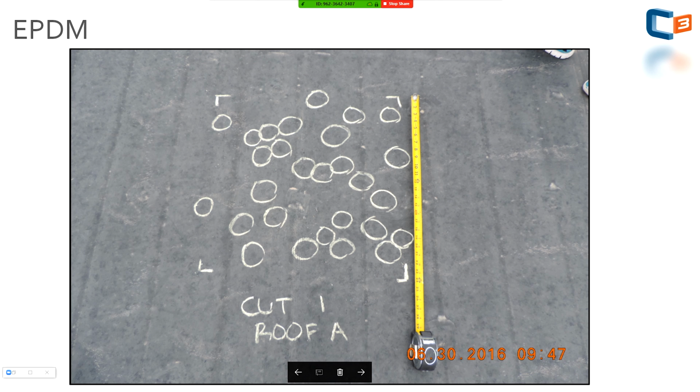So what I'm doing in this case, I can see that spatter mark. I had good collateral damage, and I'm going down and I'm trying to feel the substrate condition. If it's depressing downward, I'm going to circle those areas. Those spatter marks are evident. I can see hail impacted area. And if I find a corresponding depression, before I even cut it, I'm going to identify that location.